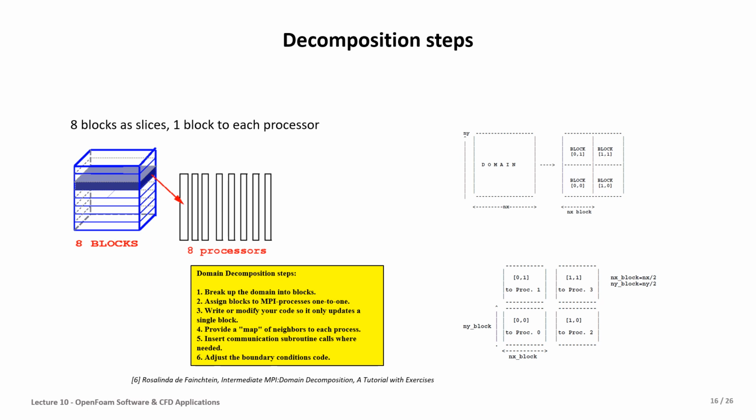And this shortly displays how we can make the decomposition of the domain. However, in this lecture, we will run the decomposition in OpenFOAM. OpenFOAM has this command and the structure to make the decomposition, and we will practically see how we make it on a specific CFD domain.